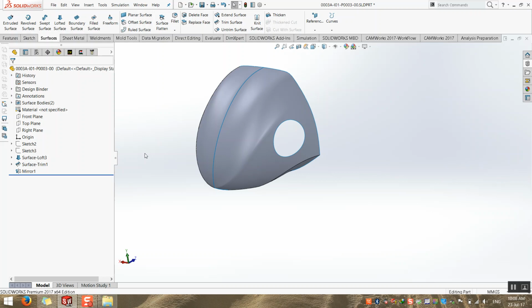If you have any additional commands to do, cutting or extrude or something like that, you need to mirror them alone with a separate command. That is why from the first time I mirror the body: any effect applied on the main body will be updated on the other side. Understand why I select body, not feature? It's a very, very important tip. Take care of these tricks, please.